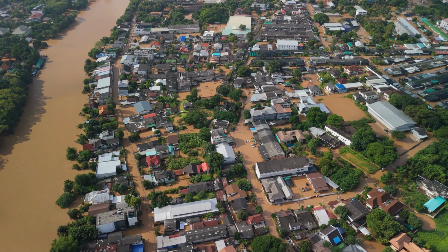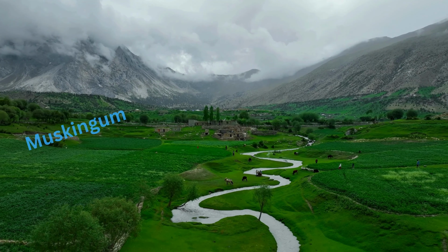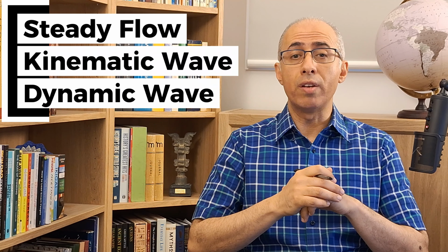Whether you're modeling an urban drainage system, a flood-prone catchment, or a storage-controlled network, the routing method and parameters you choose determine how water moves through your model. In SWMM, you're not limited to one approach. You can use a steady flow, kinematic wave, or the fully dynamic wave method, each based on very different assumptions and suited to very different problems.